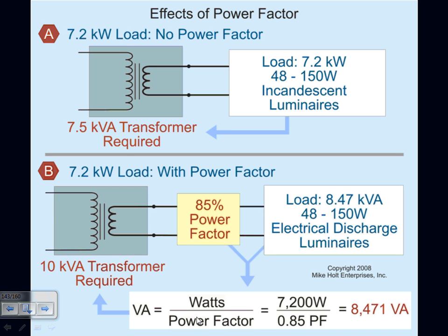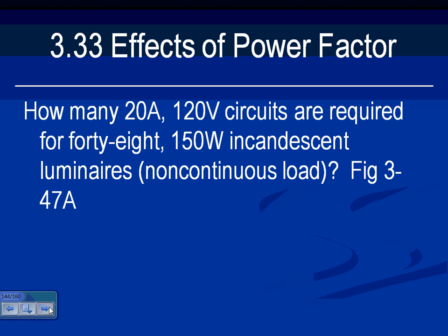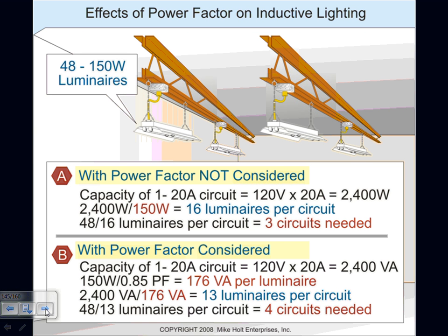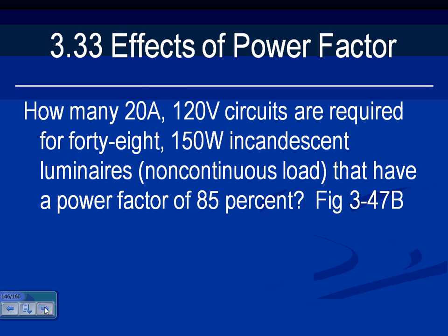I know that my volt amp is 8.75, then my transformer has to be the next standard, which is 10K. So a lot of the calculations that we will be doing, you have to take into consideration the power factor.